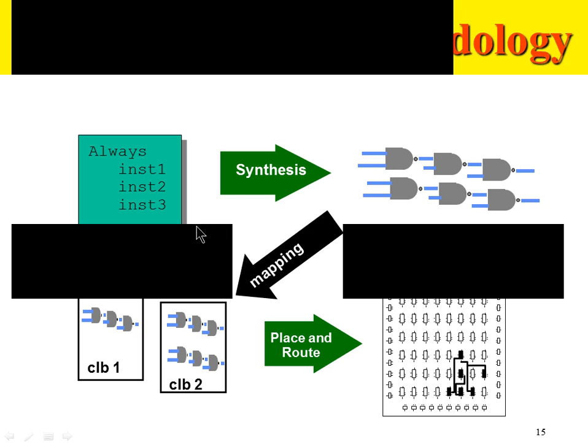This is in a generic way. So whether it's an FPGA or ASIC, in case of ASIC, the placement and routing, or the backend steps, will be much more. There is a lot of backend processing where we do design rule checks and other things. But more or less the flow remains the same.